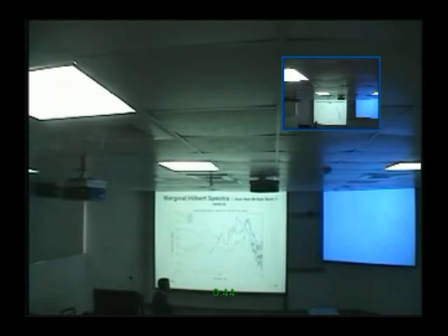What's the difference is that the bridge itself, the frequency is very tight. However, when you have low frequency, you have a heavy load, the low frequency somehow generates some subharmonics. And this subharmonic is so strong, it's even stronger than the peak. Not only that, even the noise level is already stronger than the little cars. So this bridge, span number 1, definitely has a problem. And this problem is more severe than we thought.